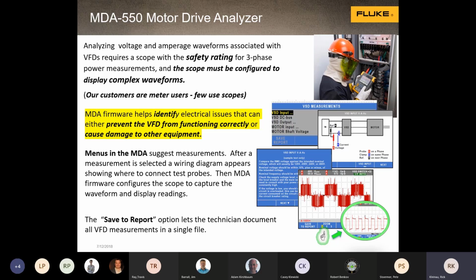It's all done automatically. In this example, I want to zoom in on the PWM signal and see individual pulses. If you're a scope jockey, you know that's easily done with the time-base button. But for those who aren't scope jockeys, we put a zoom key. Everybody understands zoom, so I just push the zoom button. There are several places where the menu system just helps you look at the waveforms and focus on your measurements and not worry about how to push buttons on the scope.